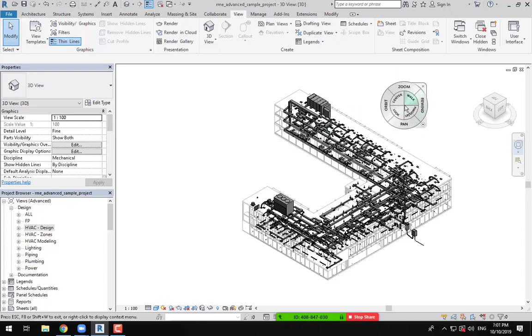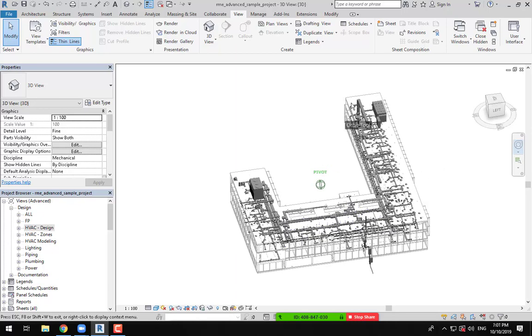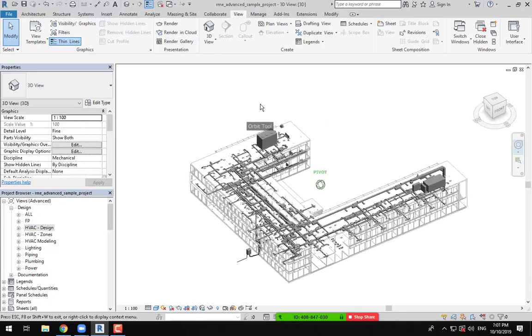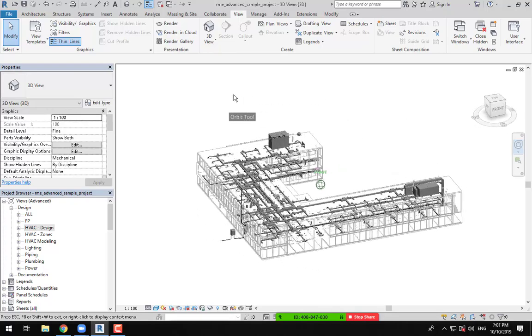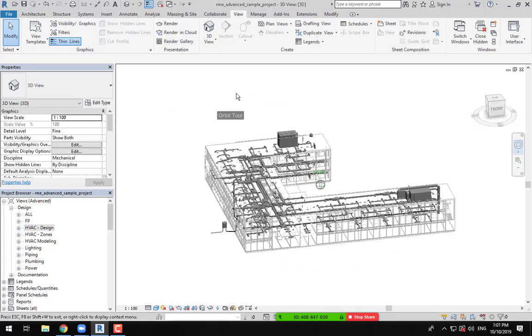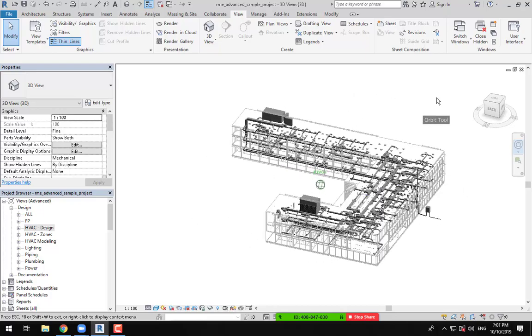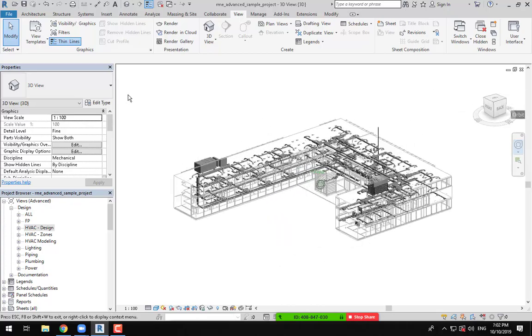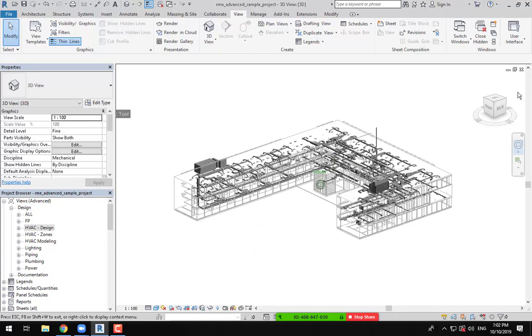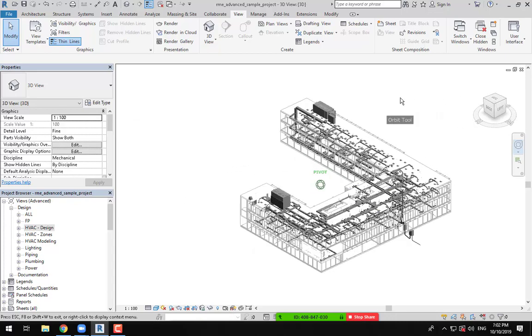This is the full navigation wheel. If you want to orbit our model, we will click on orbit and click continuously on the mouse and move the mouse right. Okay, moving the mouse anywhere, so you are now making an orbit around your model. Something else we talked about is the pivot. There is something in the center of the model, it's green, called the pivot. This pivot is the center of the orbit around the model.